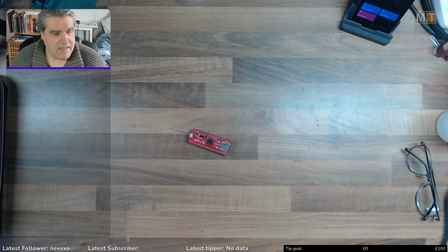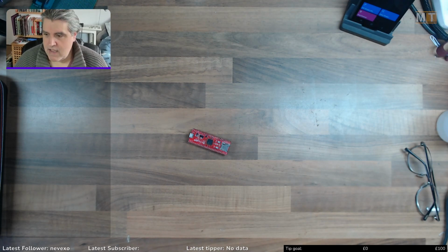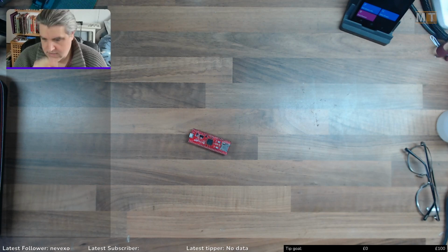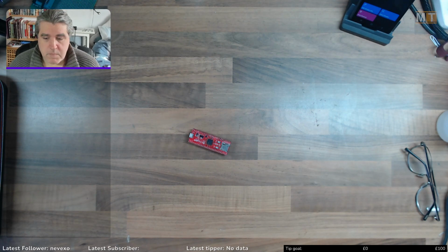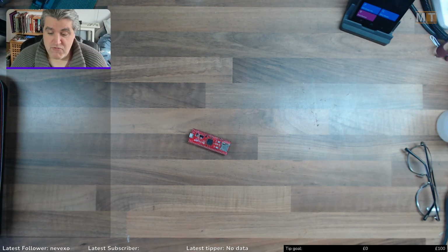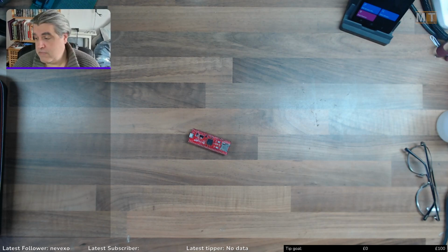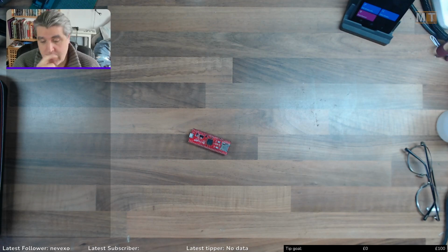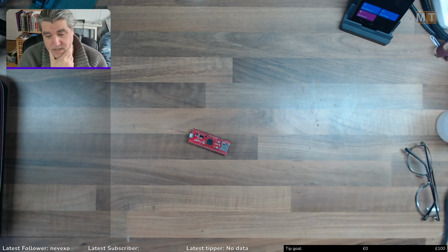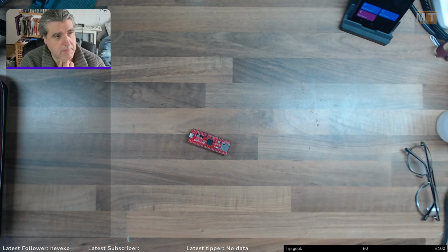Yeah, basically the logic traces he sends me are up to 16 channels. And that's pretty simple and straightforward to output as a single port on a PIC32, for example, which are all 16-bit ports. But I have choices of how I actually want to implement it.